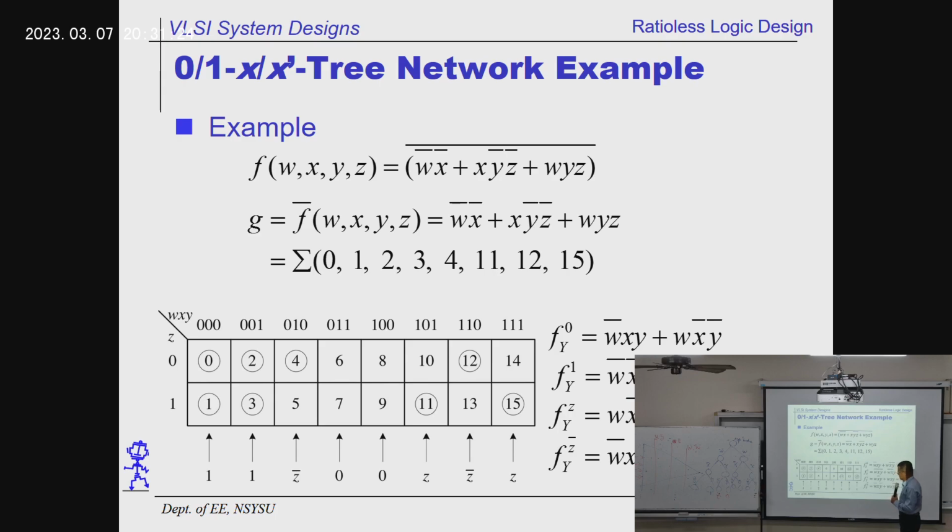And this one is kind of odd, okay? You see W, X, Y. And then you check the number here, it's kind of weird. 0, 0, 0, 0. This is 0, right? 0, 0, 0, 1 is over here. So 0, 1, 2, 3, 4, 5, 6, 7. That's another way to implement it. Of course, you can do it this way. This example is just a typical example to show you different implementations. If you decide to select different variables to decompose, that will give you a totally different residue map.